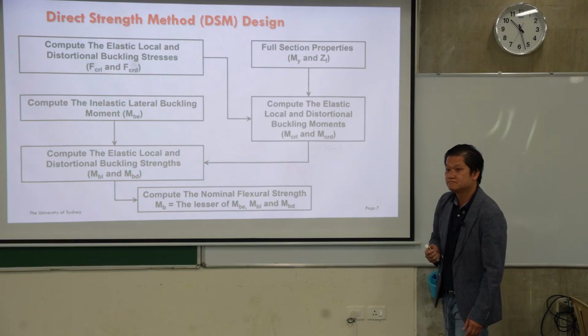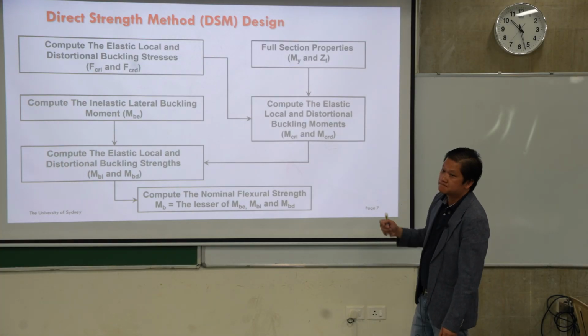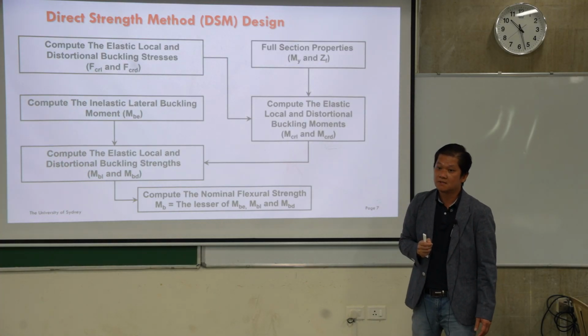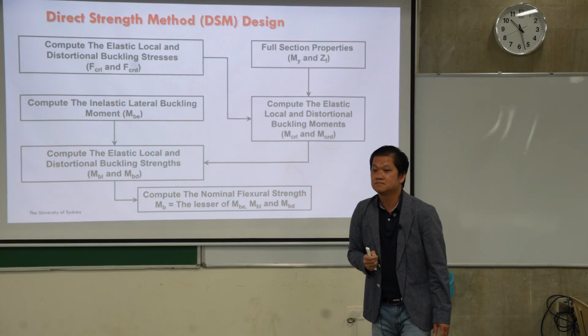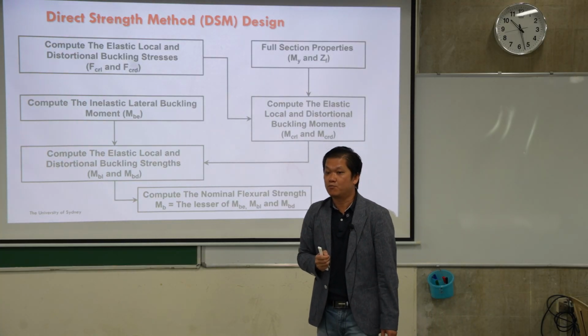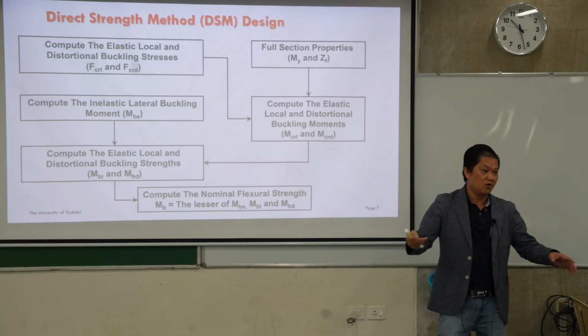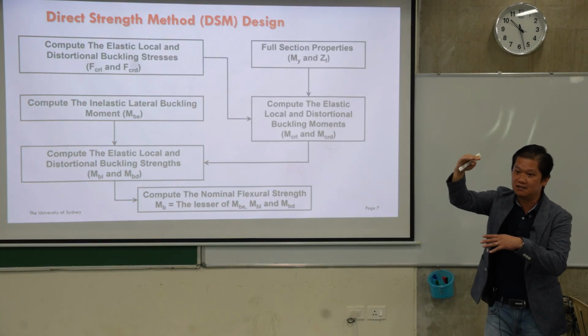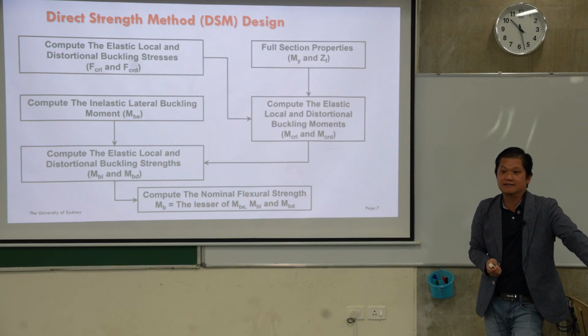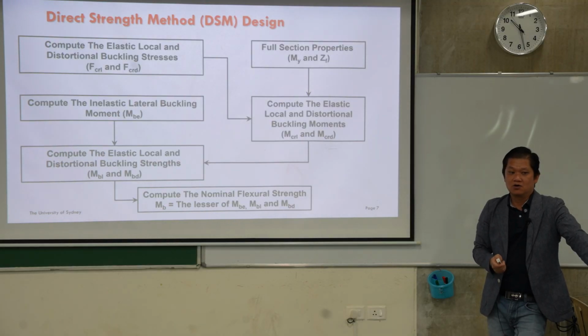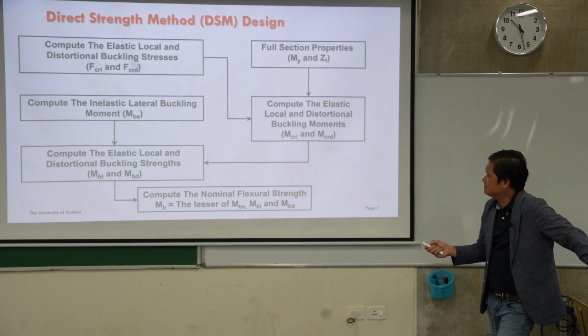Yes? For the section property calculation, can you use Zf? Yes, we use Zf. Yep, so it's just the yield moment, when the top fiber or the bottom fiber gets to the yield stress, and then that's it. So that's how you do it.